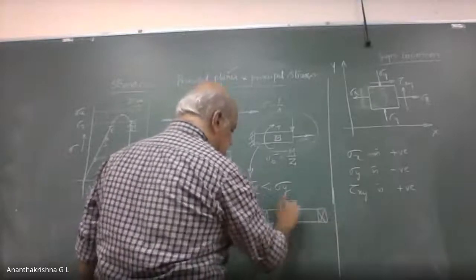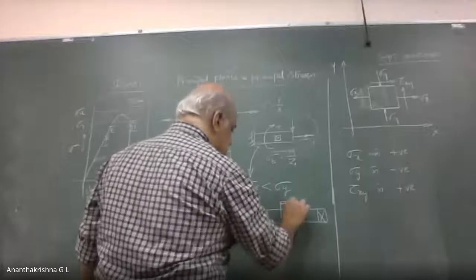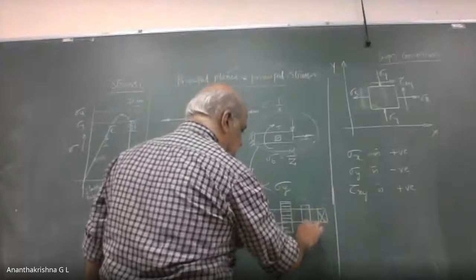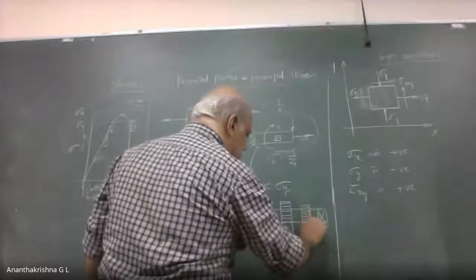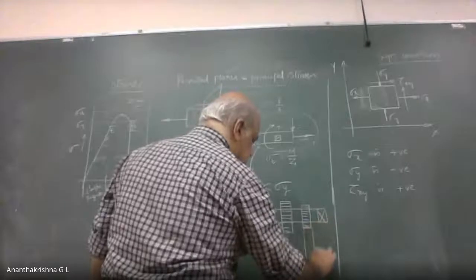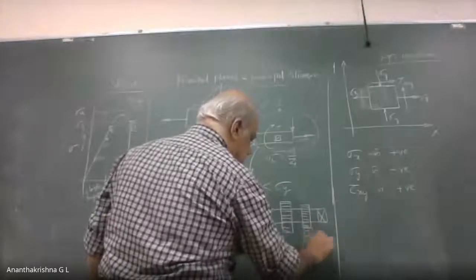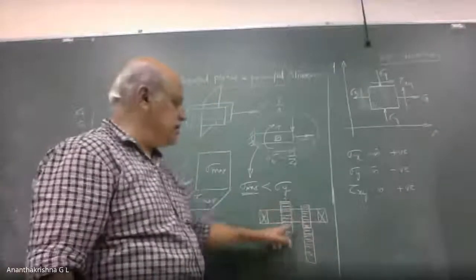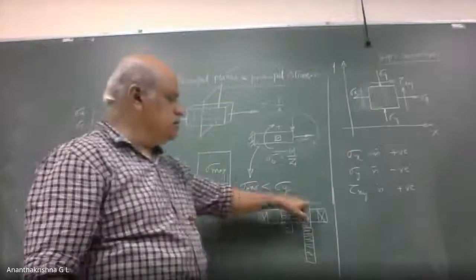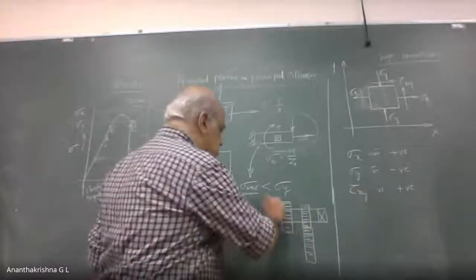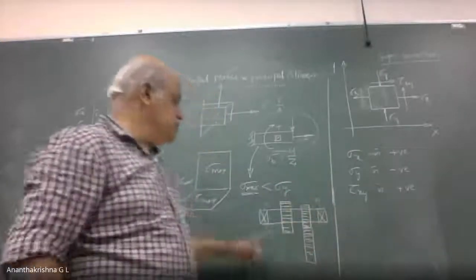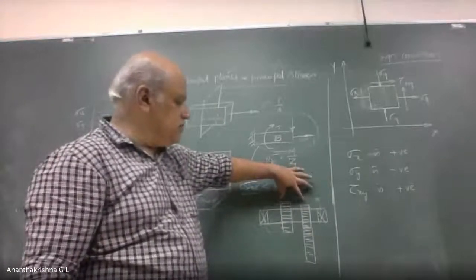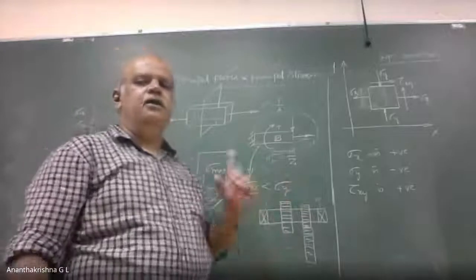On this shaft you will have numerous gears mounted, and in turn they are on some other shaft. So when you have a shaft mounted with gears like this, it will also rotate in the bearings. So the shaft is rotating along with the load in the form of gears on the gearbox shaft. So it is subjected to both torsion and bending.